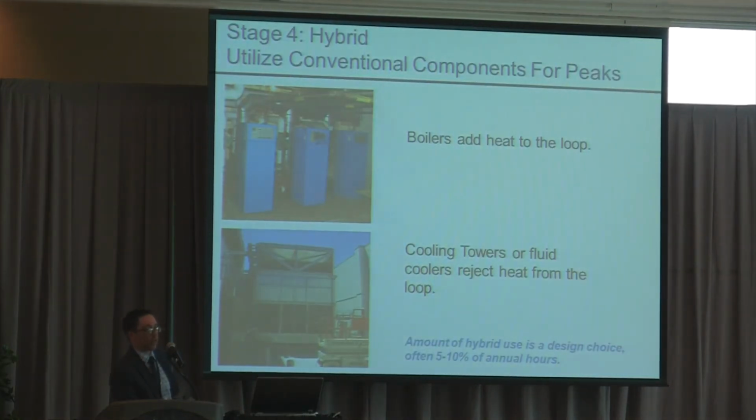Stage 4, and this is the optional stage, you can choose, driven by either space constraints or economic constraints, to design a smaller geothermal system that still provides most of the benefit. So the typical rule of thumb is that about half of the geothermal bore field capacity, if you think in terms of air conditioning tons or such, can cover about 90% of the annual load hours that would be required if you could install 100% capacity.